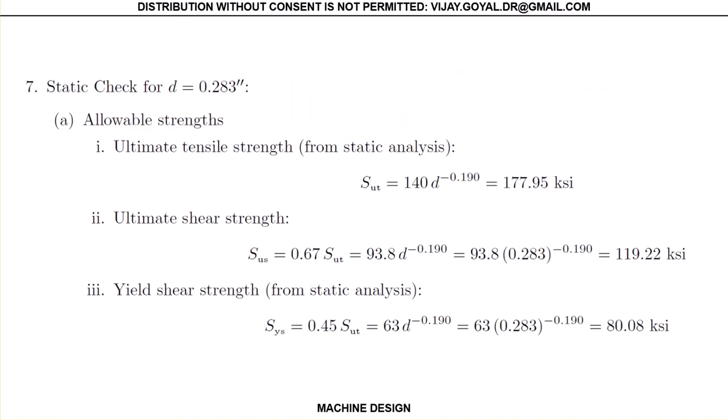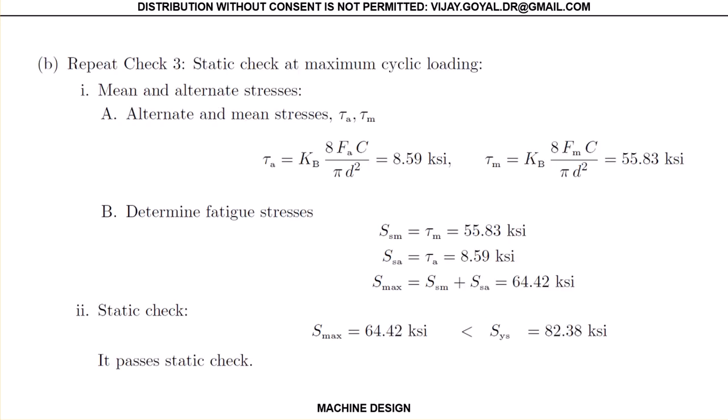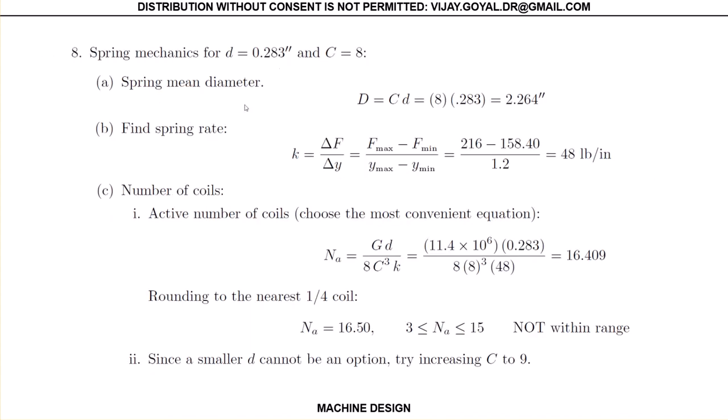Okay, and you can see that for this particular load, these are the values that you get after you replace your diameter. And then you alternate. Obviously it's going to change, right, because the diameter changed. It's bigger. So these are my new loads I have here. Then I determine your fatigue, and now you can see this is less than sigma yield, so therefore we are in good shape. Then we move on, and again, just to show you, if I use 8, what happens.